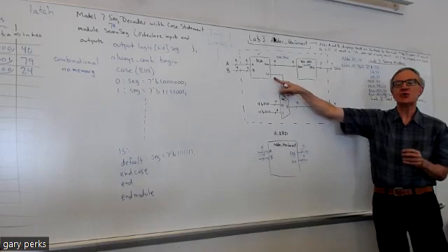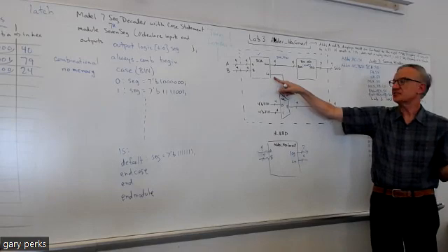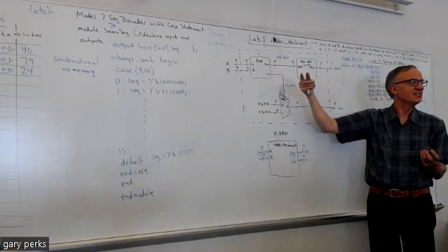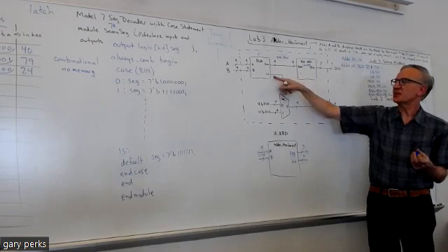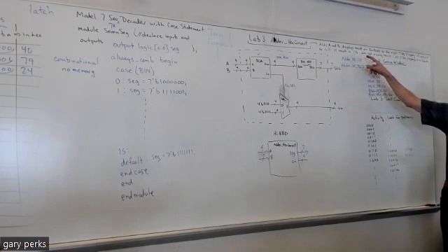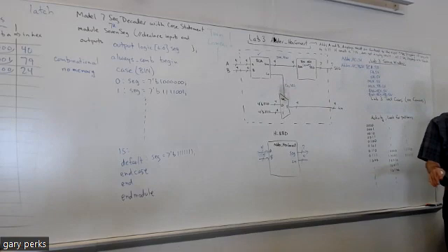Because when the carry out is a 1, that's equivalent to 16, right? So if you had 1 and all your sum bits were 0, that would be a result of 16. So if your carry out is 1, you know your result's greater than 15, and that's when we want the result not to be displayed, right? We want all the displays to be off.